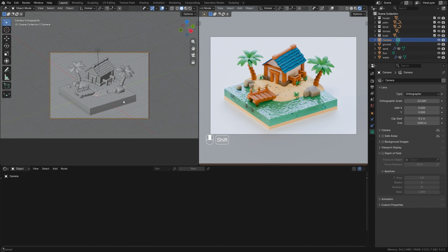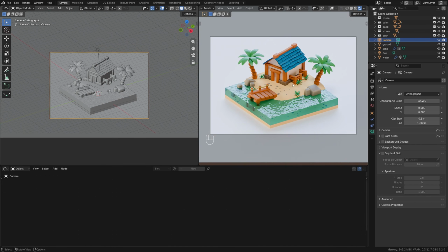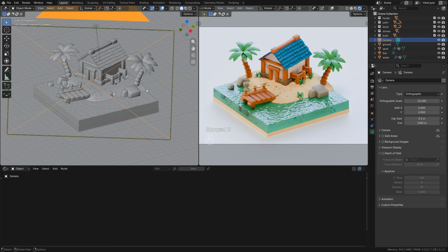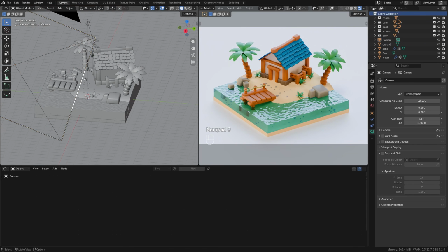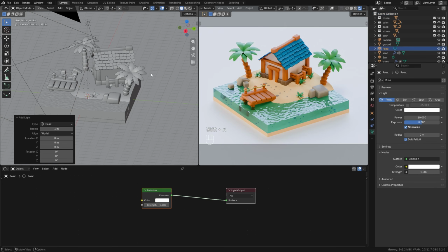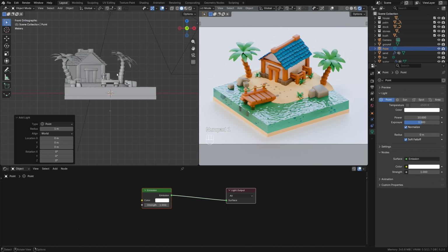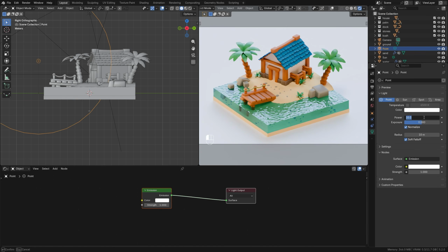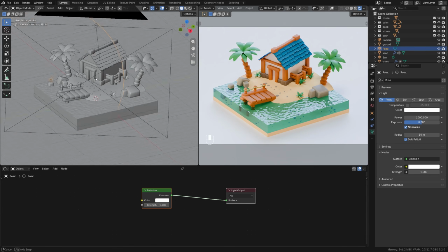Rotate, and look at our scene in the following way. And now, when we already see the render, we can additionally fine-tune all this. Well, in the first place, let's also add here one more point light bulb on front view. Shift it a little to the side, and on the lamp tab, increase its radius to 10 and raise its strength to 1000. In this way, it will lighten our scene a little for us.